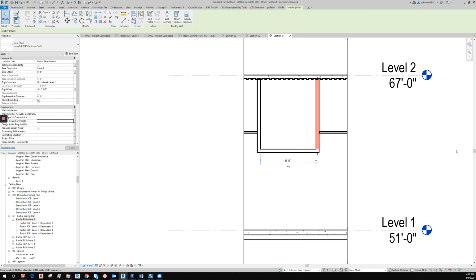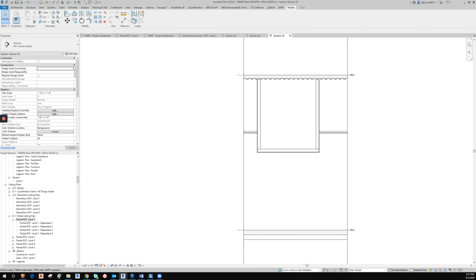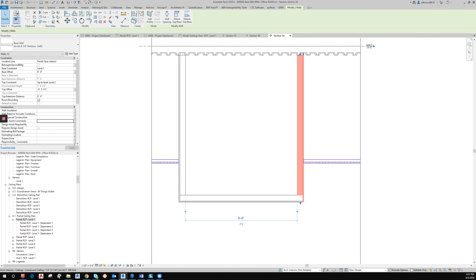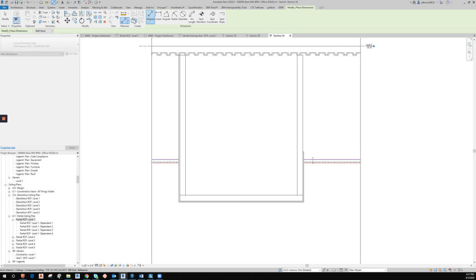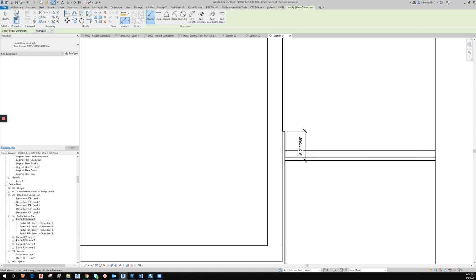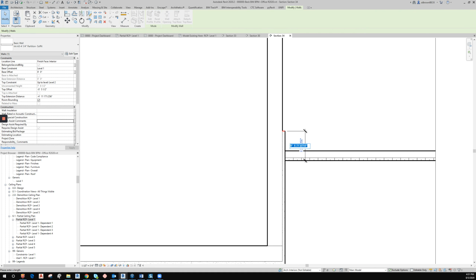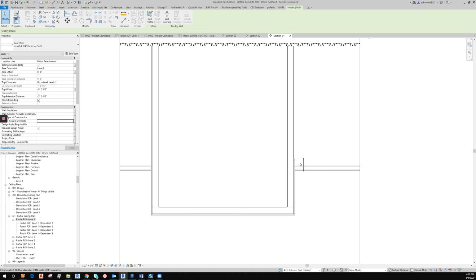walls first. Let's go, and I'm going to change the scale of this view so we can see this a little better, as I did want to show that many times you won't need the drywall to go above the ceiling more than 6 inches. So you can use the little drag arrow to do that. You can tab on that element and type in exactly 6 inches. If you look at that wall now, you will see it has a top extension distance of -5.5.